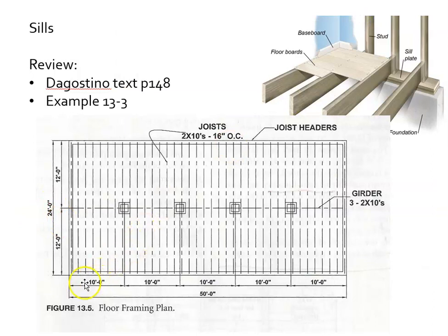If you wanted to do it most accurately, you could say 5 10-footers, 5 more 10-footers, 2 12-footers, and 2 12-footers. And that's provided no waste. So as long as there are no mistakes made, that's acceptable. No mistakes on the carpenter's part. You're basically telling your carpenters, we got only what you need.